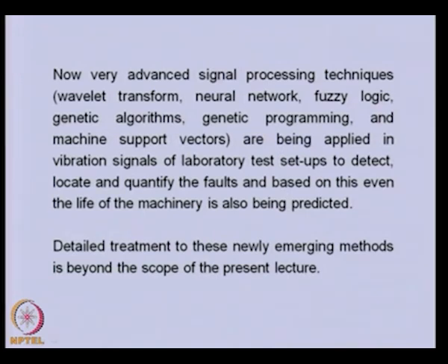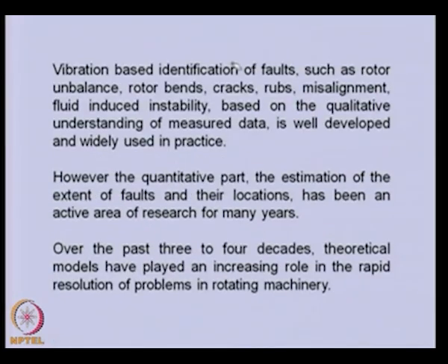Vibration based identification of faults such as rotor unbalance, rotor bends, cracks, rubs, misalignment, and fluid induced instability, based on qualitative understanding of measured data, is well developed and widely used in practice. Even this is being applied in actual machinery in industry.